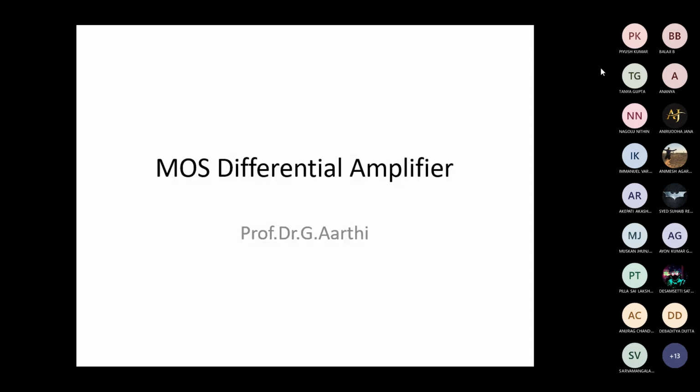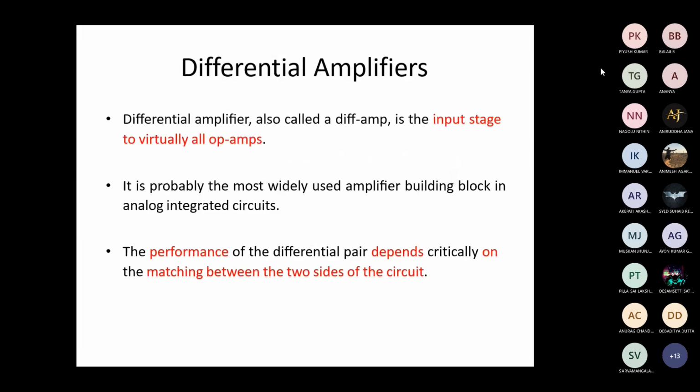So that any kind of noise or any other common input signals will be cancelled, and the output signal will be the amplified version of the differential signal. So the purpose of the differential amplifier, or if you see the applications, it is mainly used in integrated circuit applications, and other gain control, volume control applications in different areas. Okay, so let us see the theory in detail.